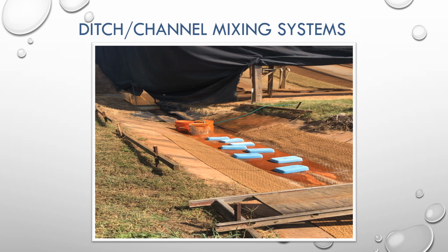Now this is a basic dewatering channel. It's a garden hose. It's maybe 15 gallons per minute. And it's important to note, again, we can do 15 gallons per minute or we can do 10,000 gallons per minute, as long as we have the right formulation, the right dosage, enough mixing, enough reaction, and particle collection.